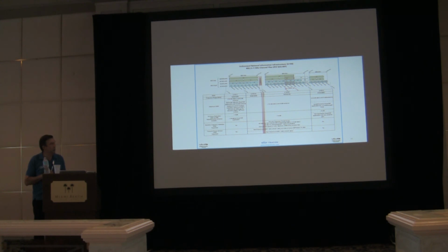Yeah, I did this because it's something that I always have to look up. I can never remember, and so it'll give you all the frequencies and all the latest channels, and whether it's 20 megahertz, 40 megahertz, 80 megahertz, or 160 megahertz. AC will never fly in the WISP environment. Outdoors, you can only get one 160 megahertz channel if you want to use AC at 160, and this one actually drops into the DFS band. So it's great in theory, it'll work great indoors, but outdoors you're going to pick up tons of interference. So it's a useful cheat sheet for you with all the frequencies on.